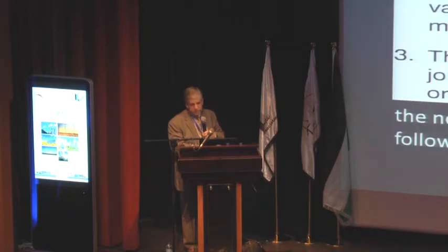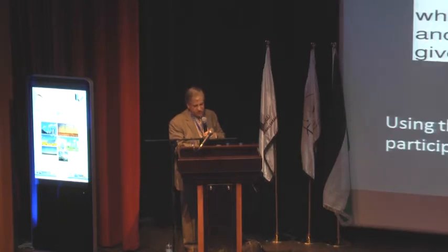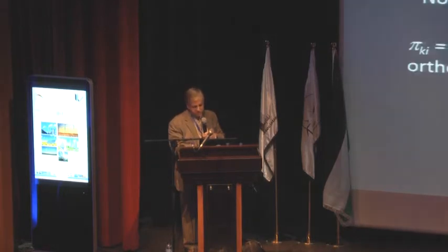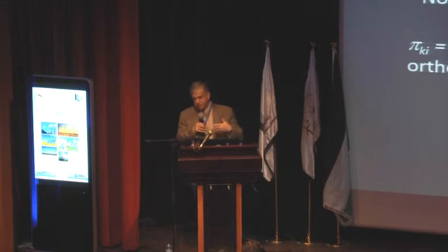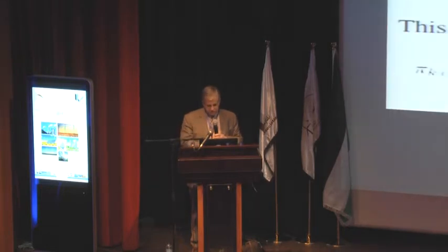But if you look at mode and state instead of state and mode, you end up with something really complicated. And you have to go through a lot of analysis. And you end up with these formulas. You know, participation factors, that formula up there, for example, end up being much more complicated when you're looking at the participation of a mode in a state. And people don't understand, what does it mean to say that a state affects a mode or a mode affects a state? Does it mean that a machine has more impact on an inter-area mode than another machine? What does it mean? So something that was sitting around for the last 35 years and everybody believed really needed to be looked at again, and it still needs more work.